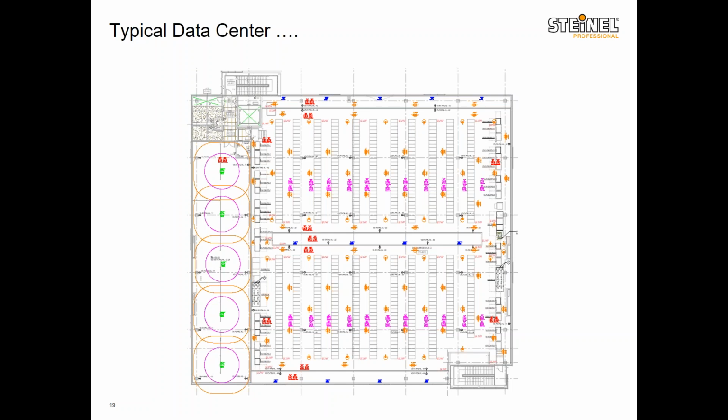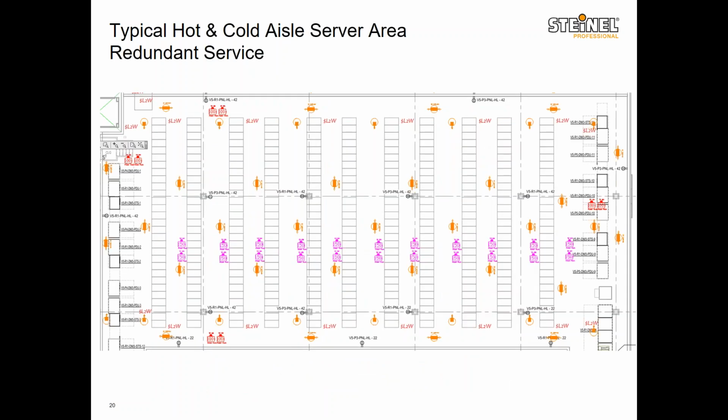So here's a little bit closer look of the hot and the cold aisle areas. So in the hot and the cold aisle areas, we treat them slightly differently. Here's an example of a hot aisle area. Within the hot aisle area, we use the IS345-24, and we insert that mask. We insert the mask so that it's only looking into the aisle and does not see any of the motion that's going down the perpendicular mount, or the adjoining aisle here.